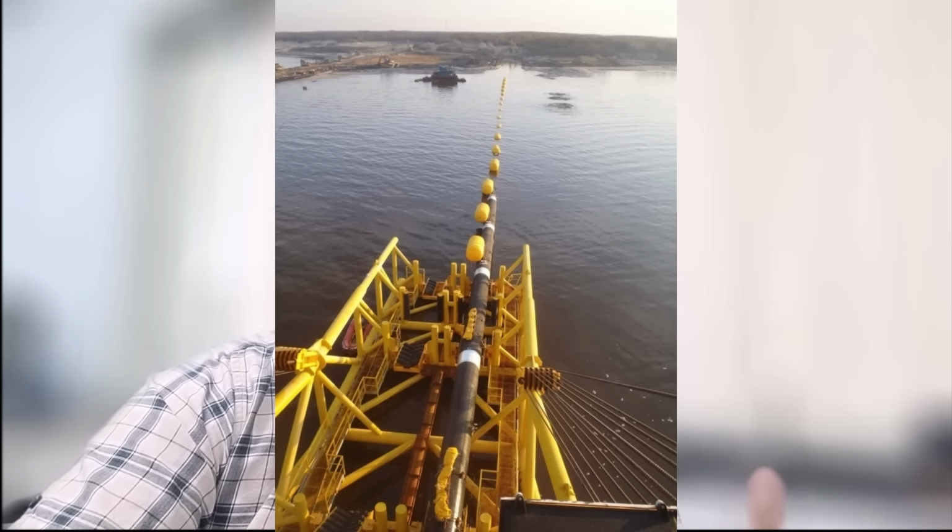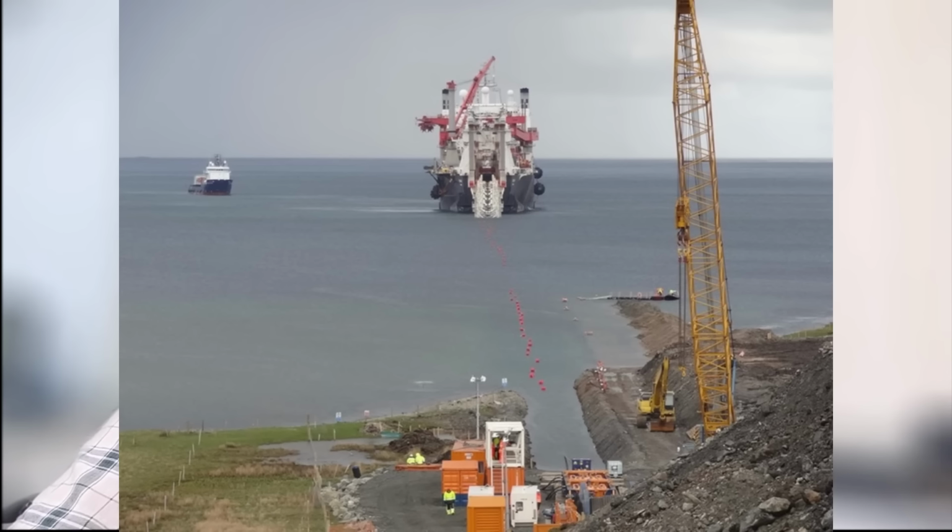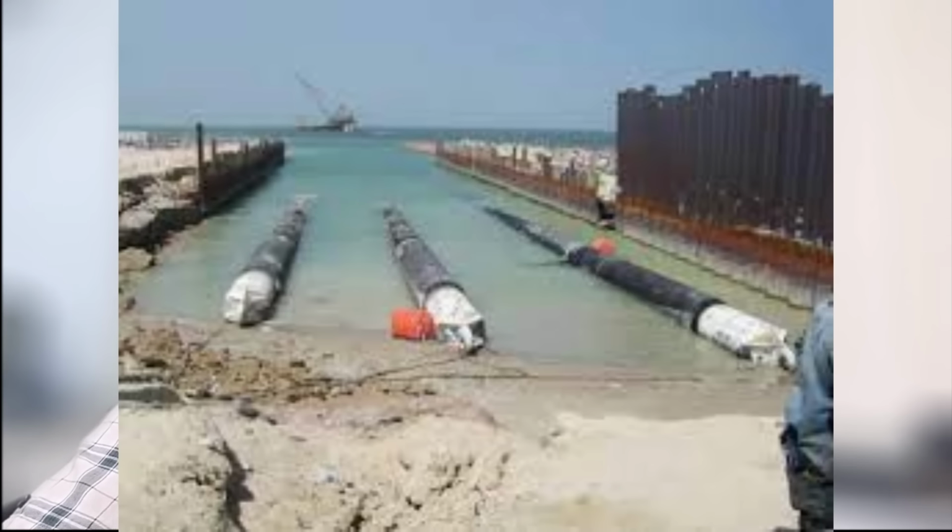Most of the times when the pipeline comes out of the stinger, some heavy duty floating devices are added to the pipeline so that the pipe does not drag on the seabed. And surveyors may need to go out in a small boat and take the fixes of the pipeline just to see that it is on the route and exactly on top of the trench. You may need to take a periodic position report when you are taking the position fixes of the shore pull, but when the barge actually starts moving ahead, crawling on the anchor, you resume to your normal pipelay position.